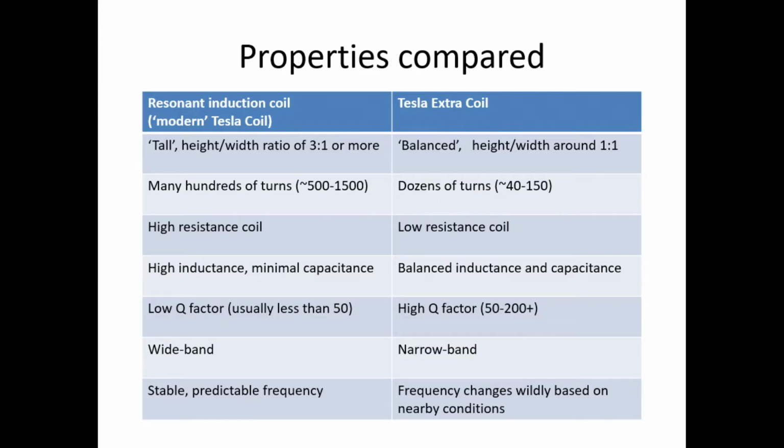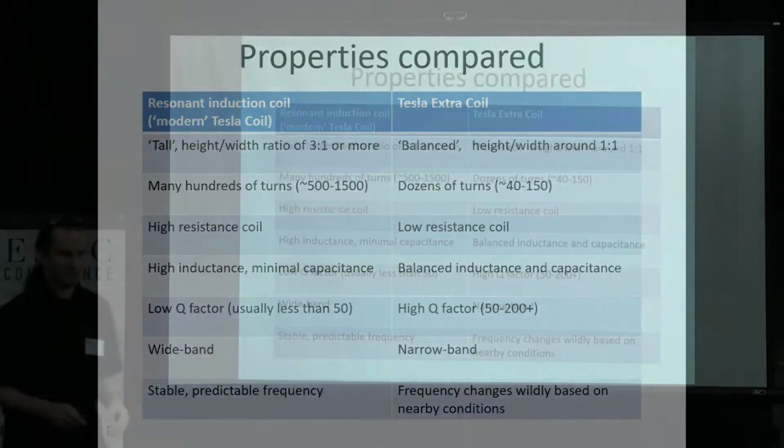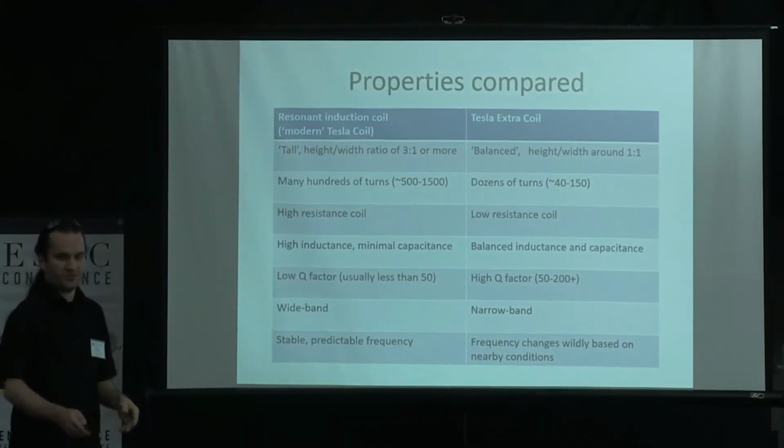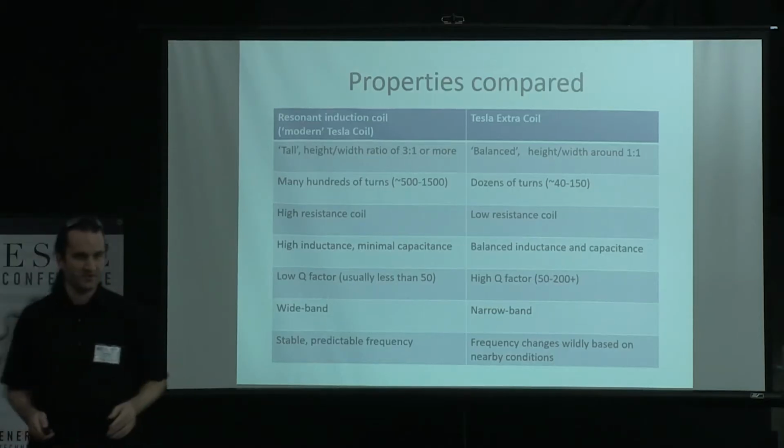It tunes over a wide range, whereas the ones we have a very high Q factor. They're very tight tuning within several kilocycles. And it's tight enough that moving your hand some small distance away from this coil is enough to throw it off significantly, so that you have full effect or nothing, just moving your hand a foot away.